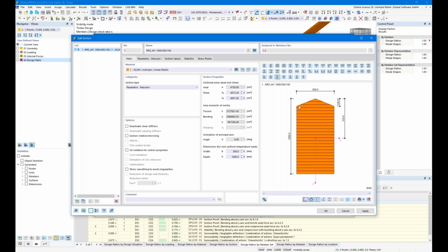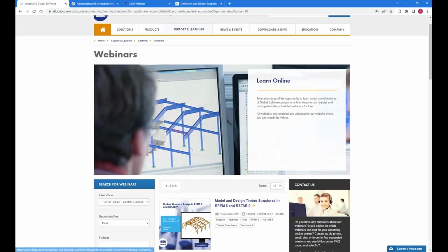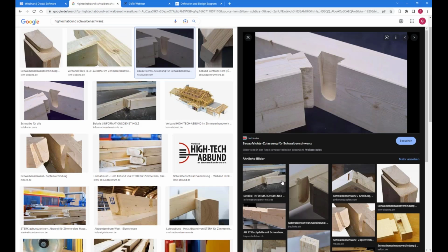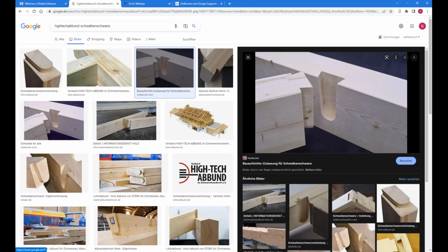But when we think about connections, so when we think about how to connect the beams to the hip rafter, where I lived, it's really typical to use dovetail connectors, for example, because you don't need additional fasteners. Of course, you will apply fully threaded screws. That's clear for uplifting forces, but that's an easier way. But of course, you will create an additional notch here. So another cross-section reduction, which needs to be considered.